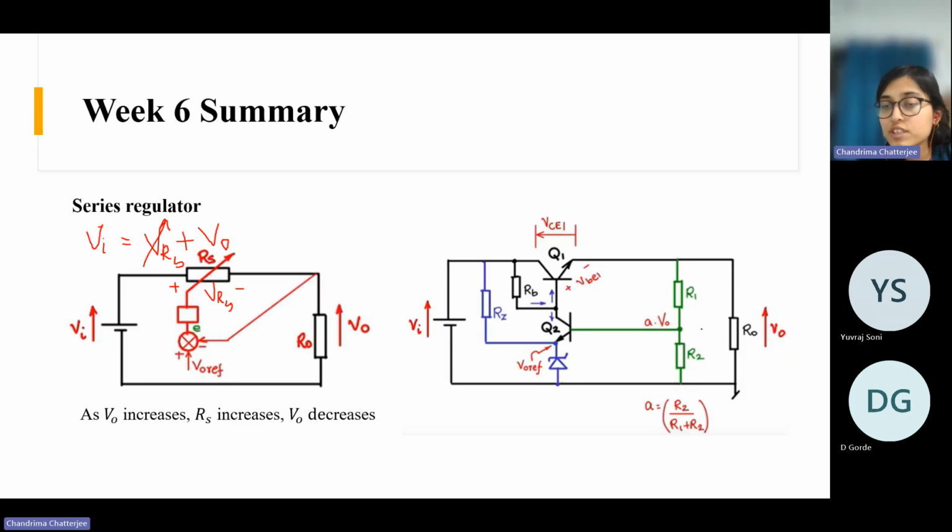And here in this part, we are tapping the output voltage, and there is a resistive divider. So we are attenuating the output voltage and we are giving feedback. So this, we were getting feedback here, right? So this is the feedback. First we are attenuating the output voltage because it may be that the BJT can't take this high a value. So that's why we first attenuate the output voltage and give the base drive to this Q2, okay, via this point.